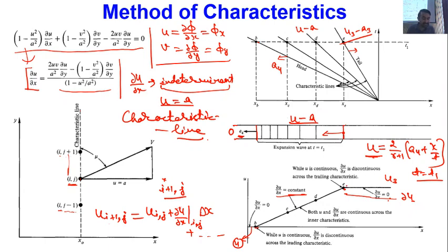So points B and C will be the characteristic points, and the directions corresponding to these points will be my characteristic directions. And what are all these expansion waves? Weak waves, weak Mach waves. So the angle of these expansion waves will be equal to mu, because these are weak Mach waves. That is the reason a characteristic direction has an analogy with our weak Mach waves also.